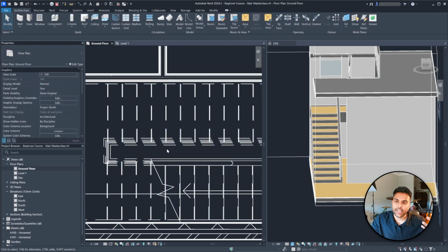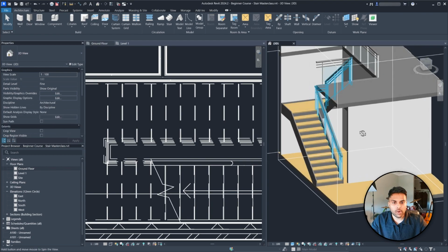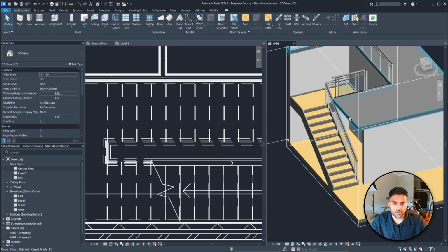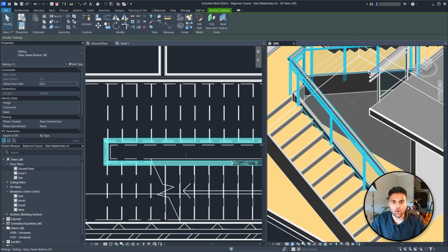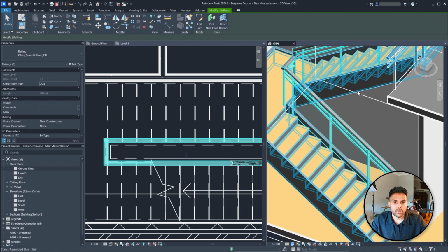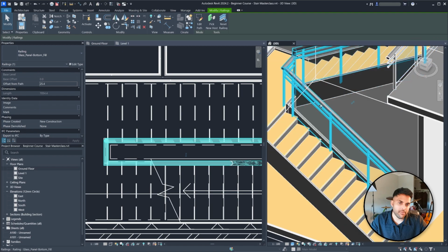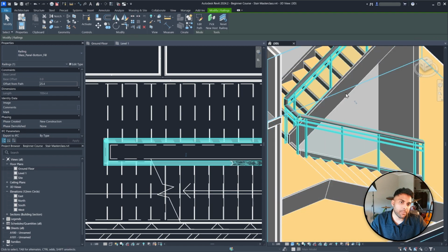I'm going to actually edit my staircase because I want my staircase not to have this small distance over here. I want the upper landing. So there's two rises, right? You're going up once and then you go up again. So you go up here and you go up again. I want them to actually sit flush, right? I want this right support to sit flush with the wall. And then I want the wall to extend just to the bottom of that right support of the upper staircase, right?